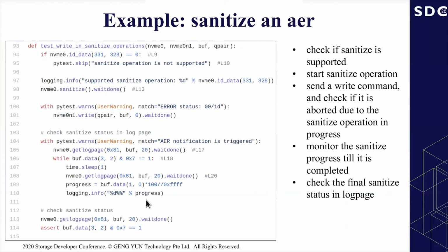When the sanitize operation completes, the SSD should send an AER completion to the host, and Pynvme will generate a warning for that AER notification. Scripts can capture it. If the SSD does not send out the AER completion after sanitize, Pynvme will report that the AER event did not happen.